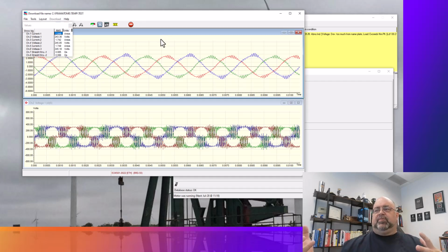It's going to give me something wrong because of the way I've got this VFD driven equipment set up. So it's just going to find something and it's going to give me something oddball. But they are actually set up 1, 2, 3 and 1, 2, 3, but it's going to do like 1, 3, 2 and 3, 2, 1 or some such thing. So what I want to do if I do this is make sure that the power factor is the highest level power factor and I get no negative numbers. And I am going to have to pause it briefly.